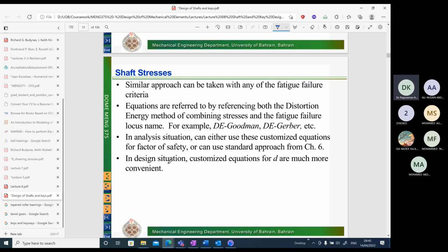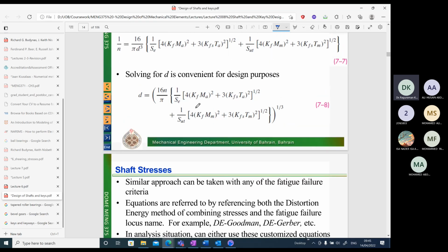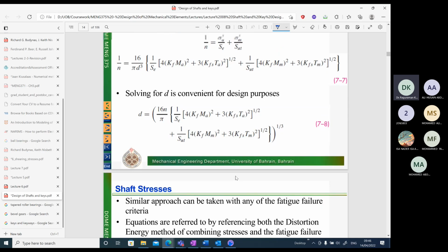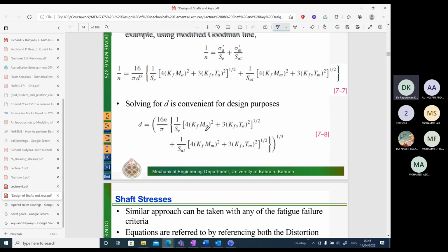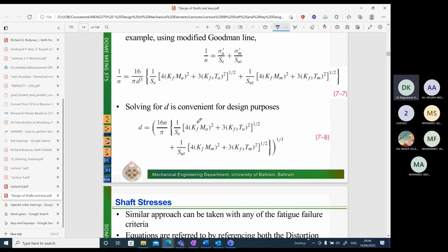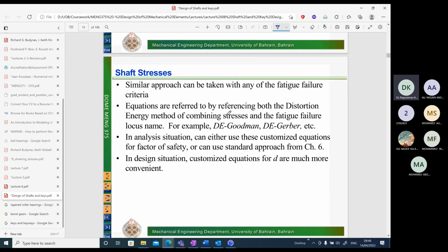Okay, so how do we use the 4 different cases? In each of the cases, for example, if you consider Goodman criteria, you need to consider the yield criteria as well. In these cases, you not only need to check for failure criteria based upon the Goodman criteria, you also need to consider yield failure criteria. We will also see the formula corresponding to that later. So in the case of Goodman, Gerber, and ASME elliptic, yield criteria must be also checked.